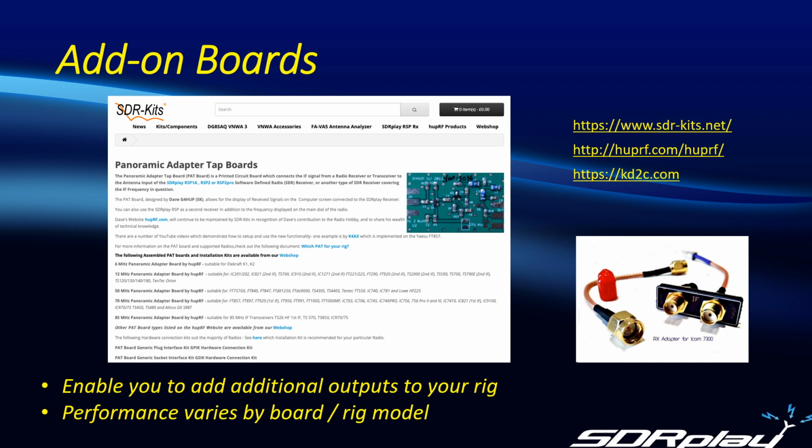someone mentioned a Dow key. That's certainly another way of doing it as well. Essentially, you're building your own external TR switch when you're doing that. I've tended to try and concentrate on the readily available off-the-shelf solutions that are out there. If you're handy with a soldering iron, then certainly you can investigate these adapter boards, or building your own solution that works in your own particular configuration. So that's kind of the RF side of things done.